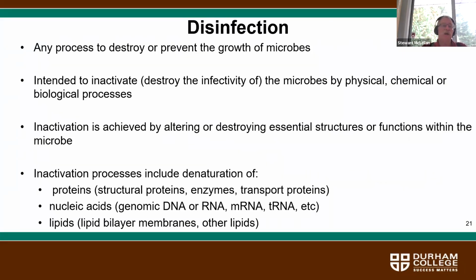Okay, disinfection: any process to destroy or prevent the growth of microbes, intended to inactivate or destroy the infectivity of the microbes by physical, chemical, or biological processes. Inactivation is achieved by altering or destroying essential structures or functions within the microbe. Inactivation processes include denaturation of proteins, nucleic acids, or lipids.